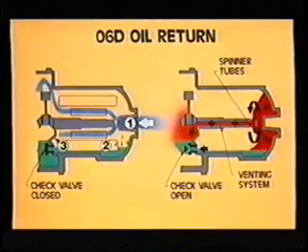All reciprocating compressors circulate a small amount of oil with the refrigerant gas being compressed. To ensure proper lubrication at all times, both the system and compressor designs must be such that oil returns to the compressor at the same rate it leaves. Once the oil gets back to the compressor, it must be separated from the suction gas stream and returned to the crankcase sump. There are a number of ways to accomplish this.